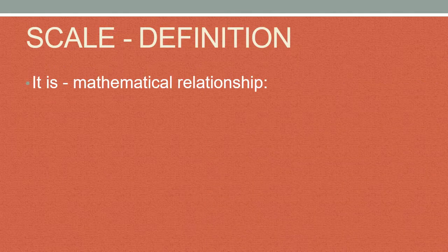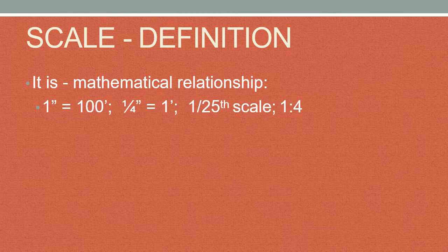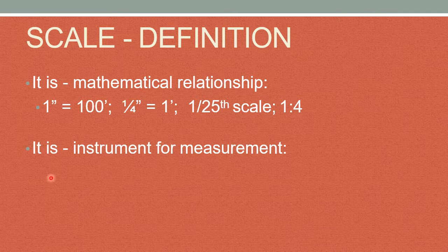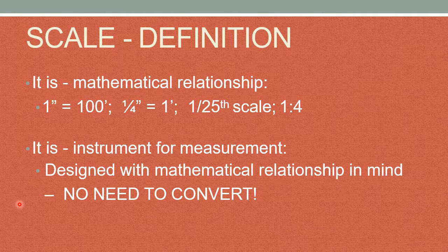Now, it is a mathematical relationship. 1 inch equals 100 feet. 1/4 inch equals 1 foot, or 1/25 scale. But it is also the instrument that we use to measure the dimensions. And when we use those instruments, it is designed with the mathematical relationship in mind. There is no need to convert.